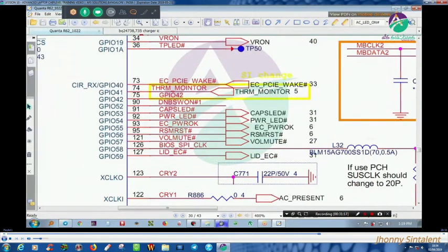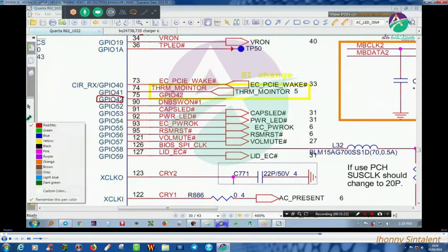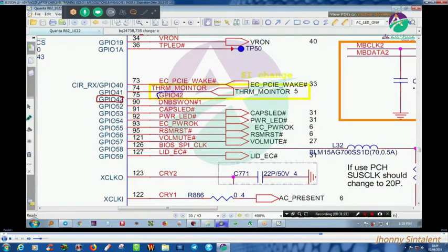So, I can see, gentlemen, I can see. So you saw that pin number 75 is an information to the IO controller, whether it is 65 watt or 90 watt. So many times you have seen that the laptop doesn't charge, or say original adapter is not present, it will not work. Okay, so how many information confirmations go to the IO controller?